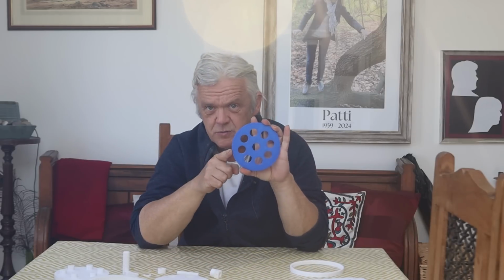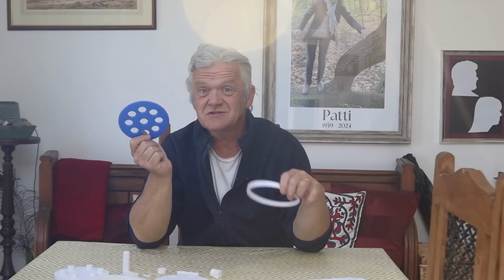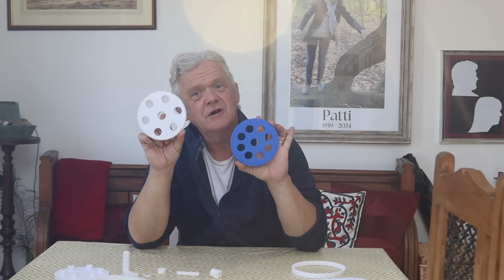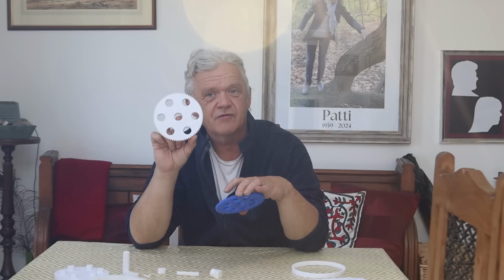We have a mechanism and we've broken it down into parts. Now, of course, what we need to do is reproduce those parts. And what I want is something about 3 or 5 millimeters deep. This one is 120 teeth, so I'm going for a 60:1 gear ratio. That's 120, that's 122. That'll give me a 60:1 gear ratio, and it's really just the same as that, but a finer tooth. And of course, the metal can cope with the finer tooth. The plastic will probably wear with the finer tooth.